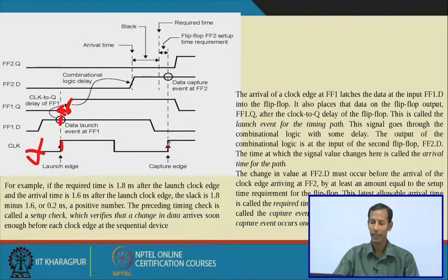Then another clock edge occurs here. At that time the value of the data is 0, so again after some time Q will go to 0.